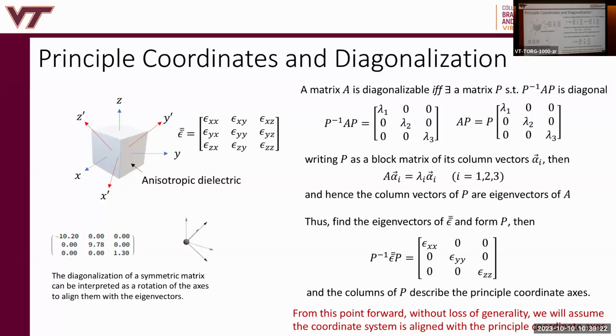For us, we solved the wave equation in time harmonics, assuming e to the j omega t. That forced our solutions in rectangular coordinates to be e to the j beta x, j beta z. We ended up with exponential eigenfunctions of the wave equation. And we know by solving a differential equation, the weighted superposition of two linearly independent solutions is also a solution. So now I can add up a bunch of exponentials with different amplitudes, and I can create any electromagnetic field I want.